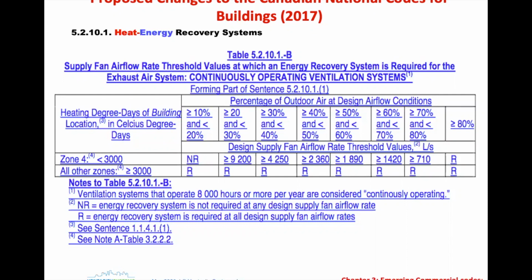I know that in British Columbia, this is commercial, they require heat recovery ventilation or energy recovery ventilation for residential and commercial applications universally. It's part of code in the whole province of British Columbia. It started in the city of Vancouver, and it's now spread to the entire province. So all buildings are requiring heat recovery, energy recovery ventilation systems by code.